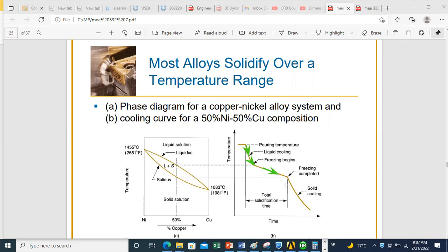Here, why do you have variation of the temperature? Because you have two different melting temperatures, and so one part of your alloy, the one characterized by a higher melting or freezing temperature, will start to solidify before the other. This is why during this phase you have a mixing of sensible and latent heat. Because there is latent heat, this decreases the variation of temperature with time. You can see this with a smaller slope of variation of temperature in this zone, because you have phase change.